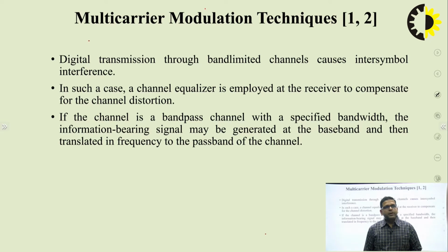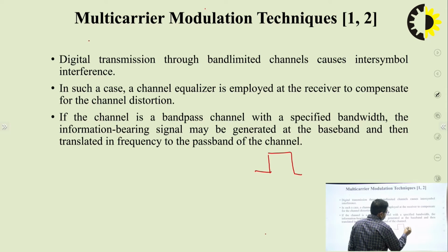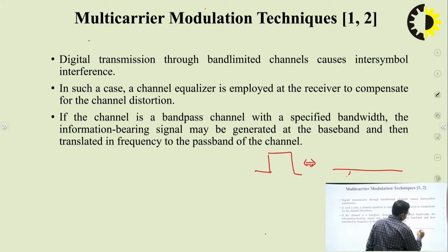Now, we will discuss the multi-carrier modulation technique. Actually, digital transmission through a band-limited channel causes inter-symbol interference. As I have demonstrated earlier, when we transmit a rectangular pulse, which is limited in time, its frequency response will be like this.